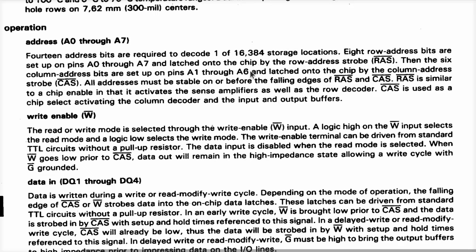Therefore, if it's wired in backwards, it will still work, because the low and high bits are ignored, which makes it symmetric. So if the low bit is on A0 or A7 and the high bit's on A7 or A0, those two are ignored anyway. My point is you'll be counting up or down, and the chip doesn't really care, provided that we're basically addressing 1 byte at a time. The RAM doesn't really care whether you store the bytes in one location versus another.